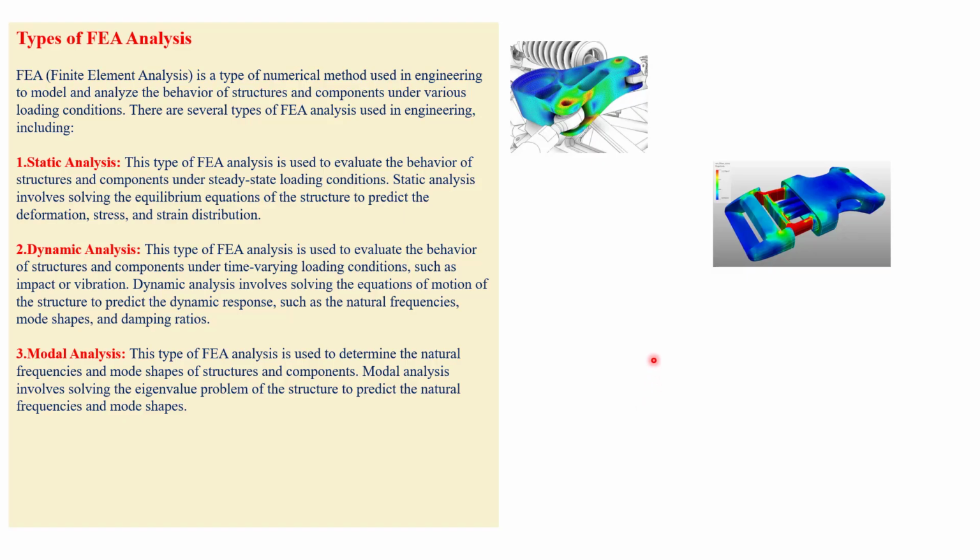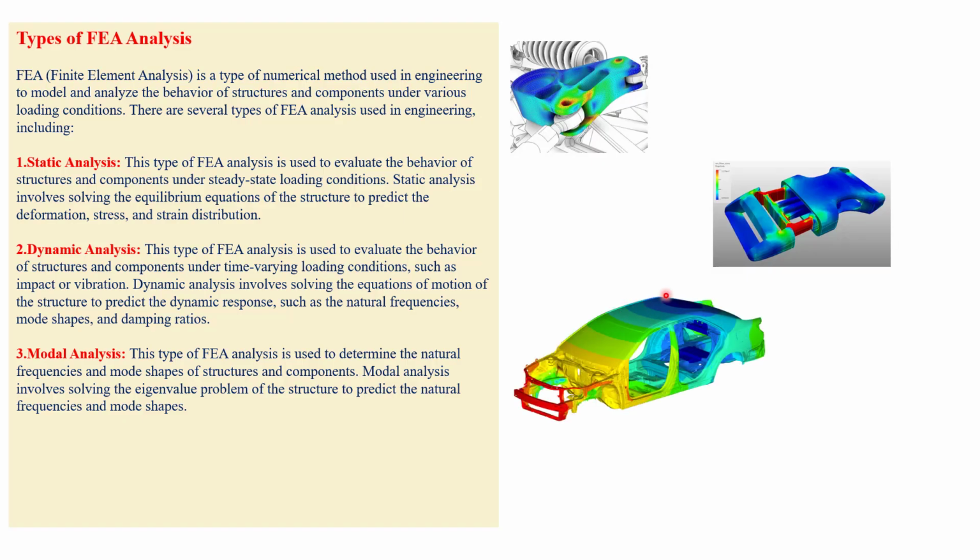Yeah, I could see if you have the BIW here, we have adhesives, RBE2s, RBE3s connected to this complete BIW portion. And now there are so many modes, very important. In the automotive domain, we deal with the torsion and the bendings.